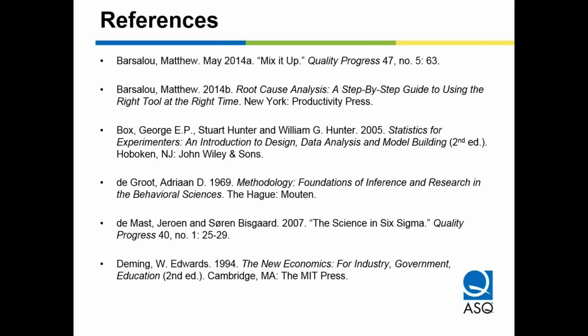Do you need one person to just do legwork carrying around parts? Okay, that's an extra warm body you're going to need. What knowledge do you need? If you have a metal part that's been machined and it failed, you may need a machinist or a machining expert. You might need an expert in the process itself. You may need a metallurgist.